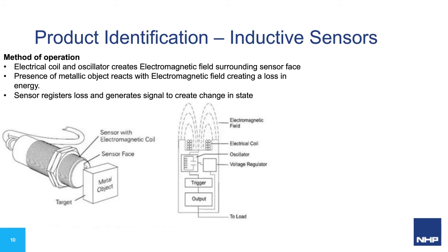So you prefer a flatter, larger surface pointed at the sensor face, and different materials interact differently with the magnetic field. Metals that are magnetic or ferrous are easy to detect as they will interact with the magnetic field of the sensor and dampen this more. So you won't lose much of the advertised sensing range, if any. While metals that are non-magnetic or non-ferrous are difficult to detect due to the weak magnetic field and interaction, so it shortens the advertised sensing range.